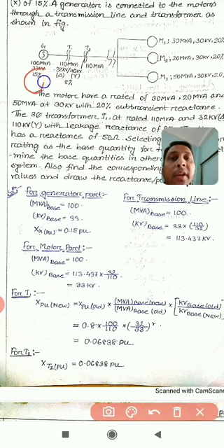So we will convert the reactances given here: 15%, 8%. For T2 also it is 8%, same as T1, and for the motor it is 20%. Percent is nothing but per unit. What we say as 15% means in per unit it is 0.15, 8% means 0.08.